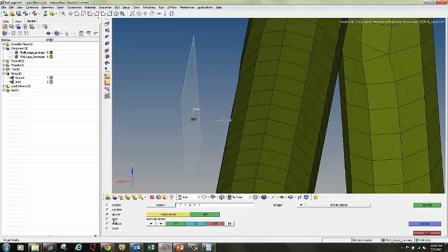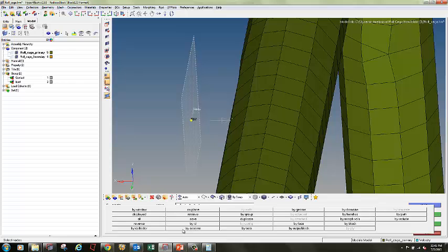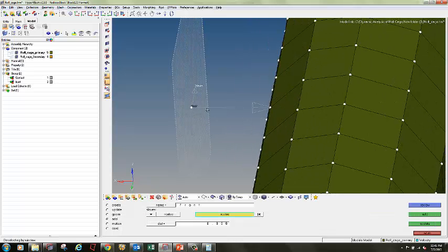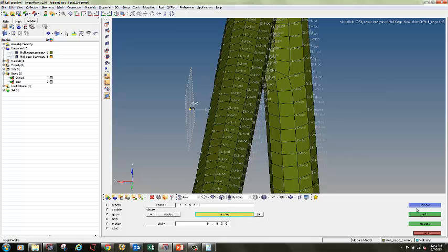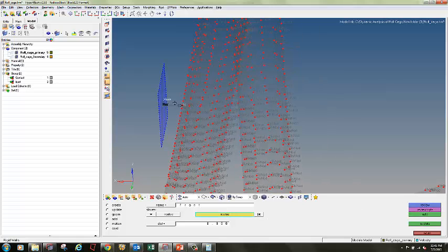Then go to add, select the nodes, all, and deselect this node of the wall and click on add. Now you have to review this. So it has to be blue where the impact will happen, and the nodes which are going to impact are red. So those are the things which I have to add to create the wall. I will click return.